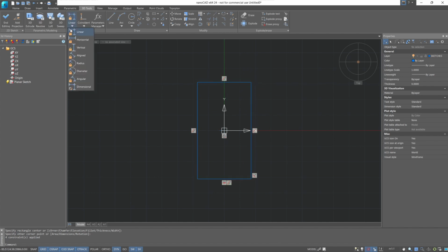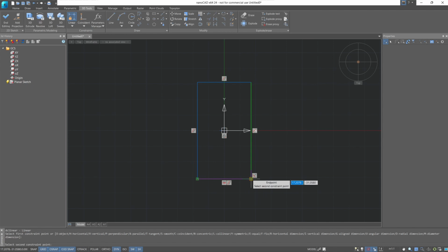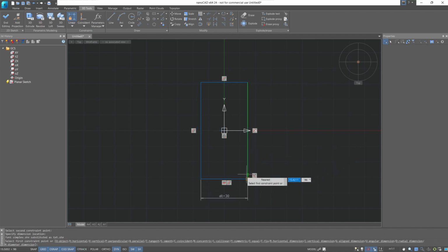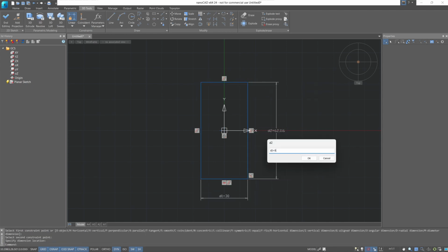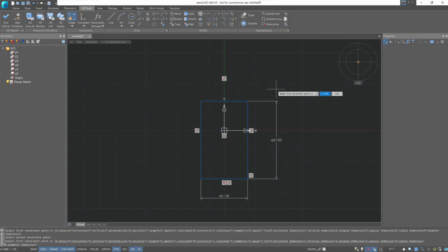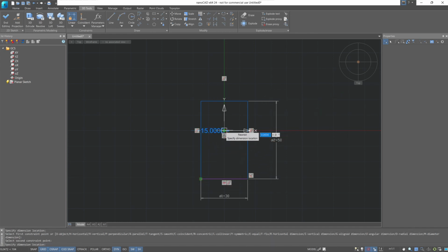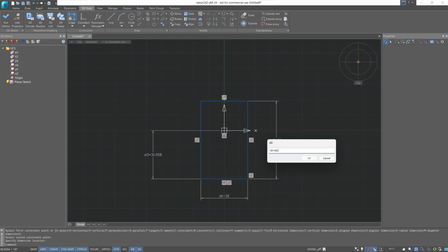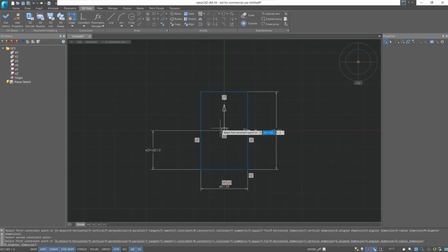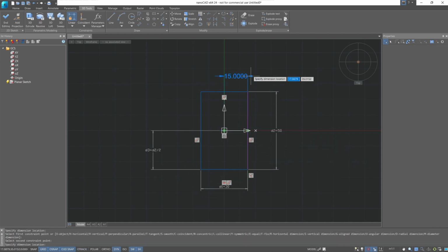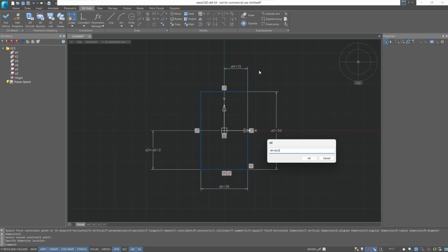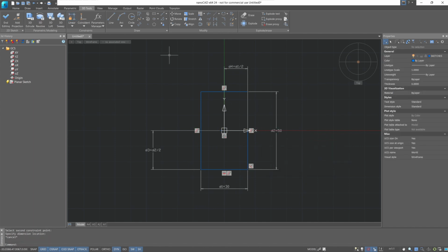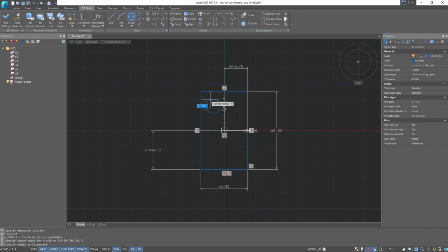Let's add dimensions. Specify the length as 30 and the height as 50. To align the sketch relative to the origin, add dimensions to the center. As in the previous example, specify them in terms of d2 divided by 2, and the second dimension d1 divided by 2. Draw an arbitrary circle at the top of the rectangle and complete creating the sketch.